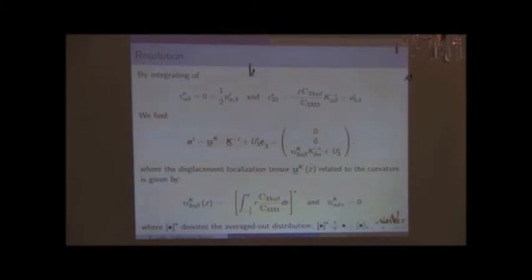So basically, when the plate bends, because this side is under tension, it gets thinner, and because this side is under compression, it gets thicker. You just integrate this strain to get the out-of-plane displacement.